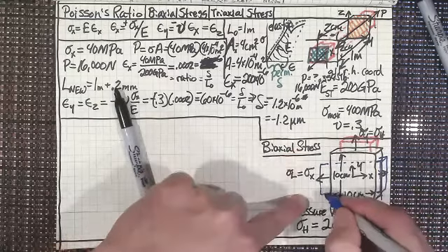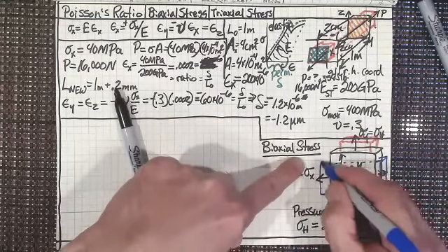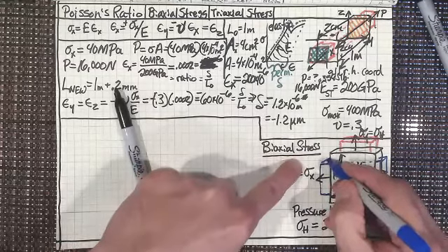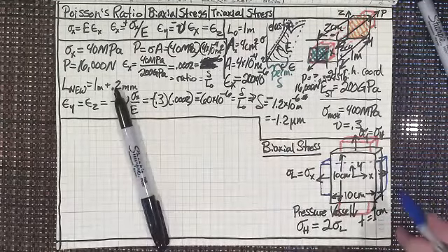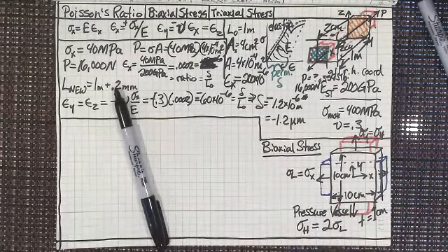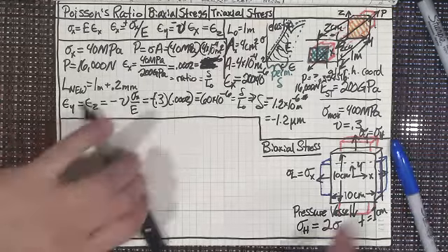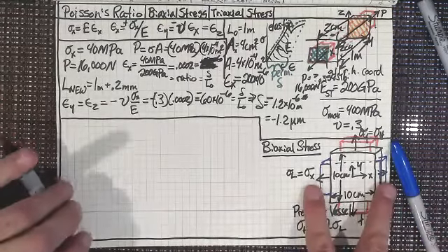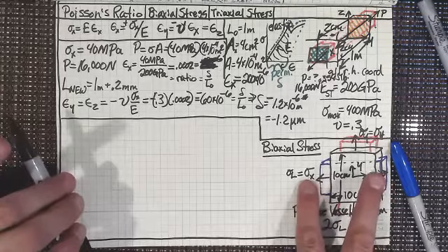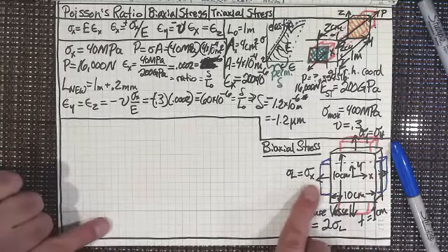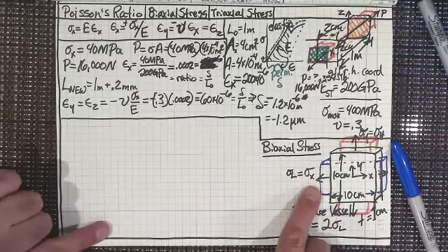And it wants to make it thinner in the other direction. Does everybody see that? Aren't those competing interests? When I look at sigma sub x, isn't the strain in that direction sigma sub x divided by E?